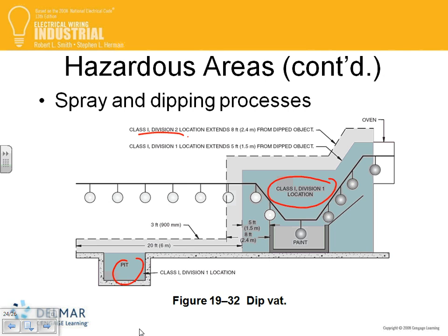Here's when we design, Brad, hazardous location. Rule number one, avoid putting equipment in a hazardous location if you can. If I can put my panel in a non-hazardous location, should I choose to put it in a hazardous location? No. You put equipment in a hazardous location, class 1, 2, or 3, guys, only if you have to, because it's expensive. If this is a class 1 div 1 location, I can put my panel outside and my disconnect outside, guys, and just bring the equipment itself here. So try to avoid using it. If you have to, then you have to follow the rules. Painting.